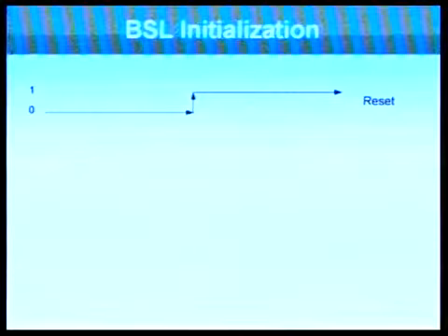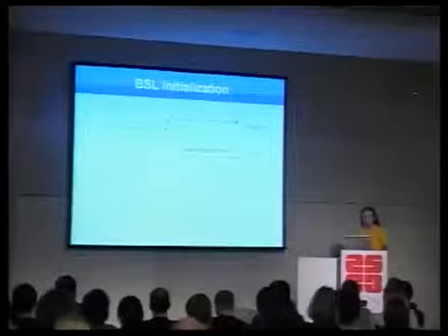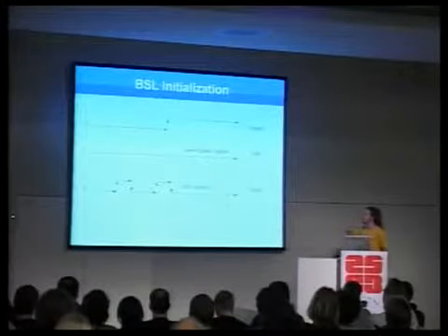Now, to start the BSL, keep in mind this is a microcontroller, it has no innate operating system. Usually you turn the microcontroller on by raising the reset pin from 0 to 1. And if your test pin remains grounded throughout that, then the user program will begin. If you send 2 pulses, and sometimes this is backward on another pin, and the second pulse falls just after the reset line goes high, then instead of pushing the reset vector into the program counter, it pushes a vector found within permanent masked ROM.